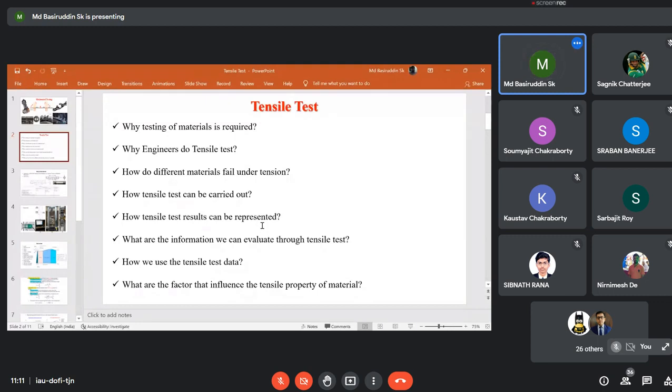Though you have followed the ASTM standard, when you fabricate the specimen, sometimes manual error can remain there. Let's say you have fabricated a cylindrical specimen and the gauge length is 25 mm in one sample and the diameter is 5 mm. In another case the gauge length is 26 mm and the gauge diameter is a little bit different compared to the previous one. So in order to handle that problem, you have to represent the data such that you get quite equivalent results.